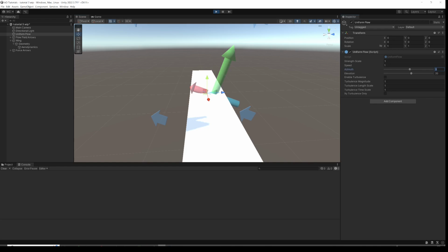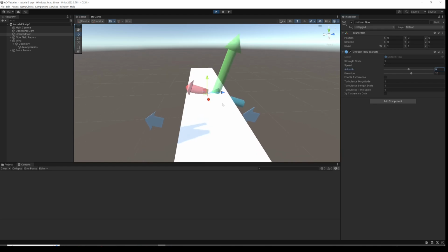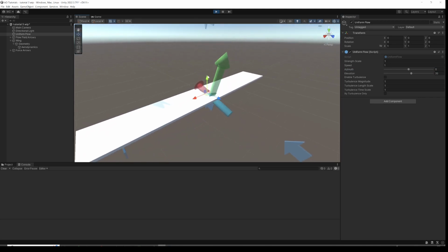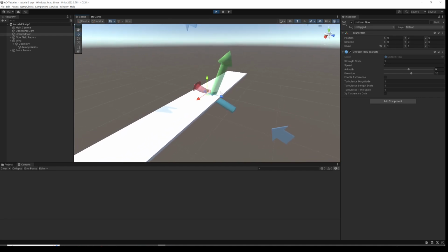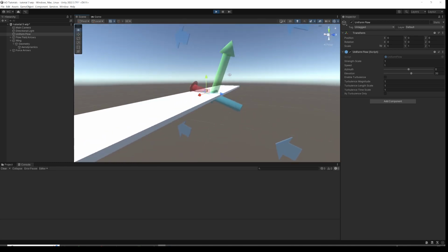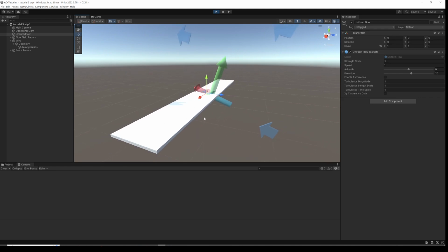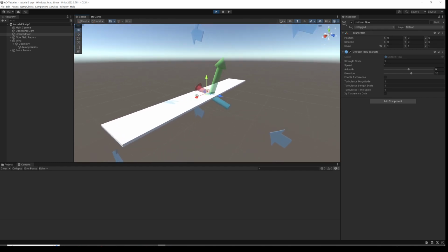The other thing which we're interested in here in terms of our lift modelling is it really matters where the lift acts on this wing. So imagine this really was a ruler. If the lift's acting to the front of it, the front will tip up when it's flying. If the lift is acting at the back, it'll tip the other way. So for an aircraft, it makes a big difference where the lift acts. And from a technical perspective, the location of the lift is called the aerodynamic centre. If we've got a flat plate wing like this, the aerodynamic centre is coincident with the centre of pressure, which is probably an easier concept to understand.